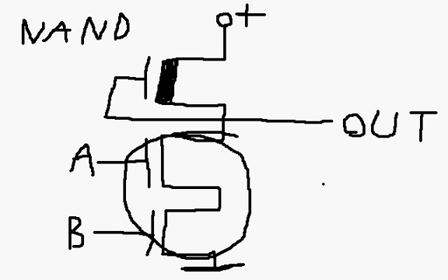So the truth table for a NAND gate looks like this. So basically, in an AND gate, 1 and 1 would give you 1. So in a NAND gate, that gives you 0, and everything else gives you 1. So basically, as you can see, if A and B are both on, then that pulls the output down to 0. Otherwise, there is no path to ground, and so it stays high. It stays 5 volts, assuming 5 volts is your high logic position, which it is in TTL.